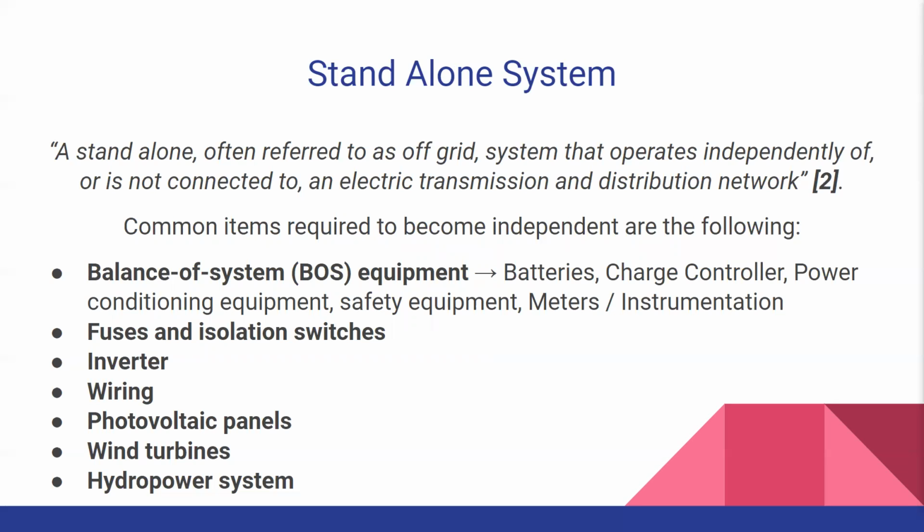Standalone, often referred to as off-the-grid, is a system that operates independently and is not connected to an electric transmission and distribution network. The common items required to become independent are the following: balance of system equipment, batteries, charge controller, power conditioning equipment, safety equipment, meters and instrumentation, fuses and isolation switches, inverter, wiring, photovoltaic panels, aka solar panels, wind turbines, and hydropower systems.